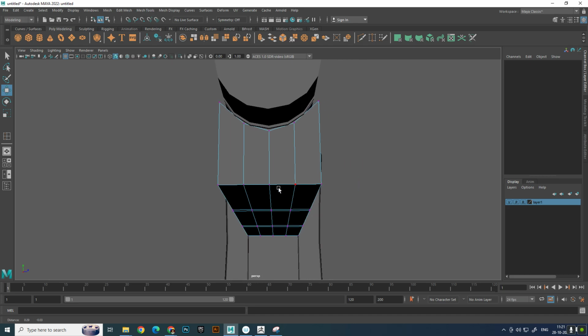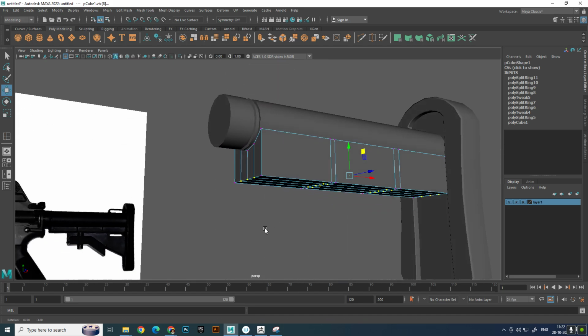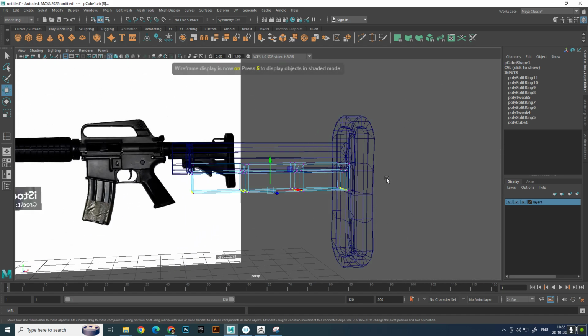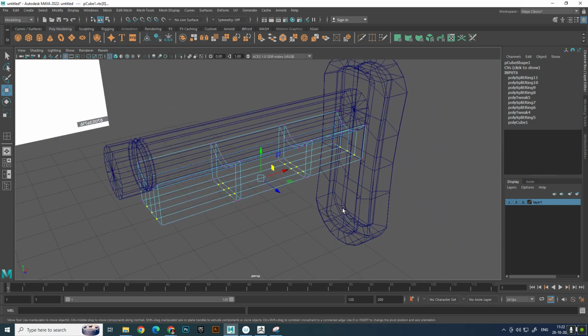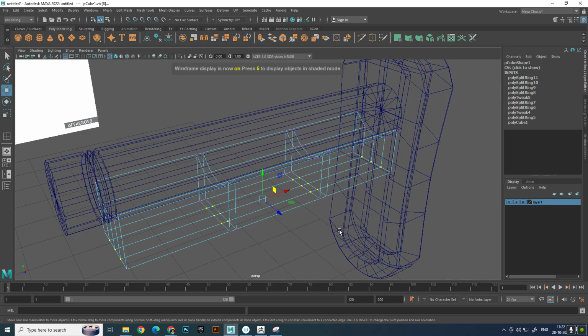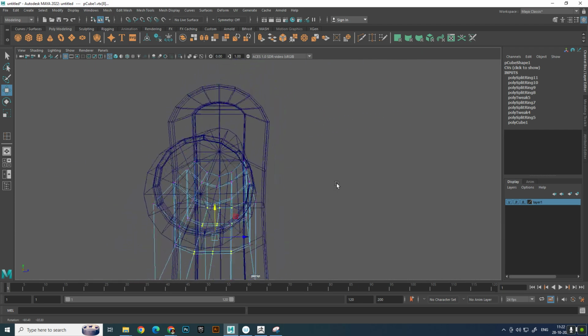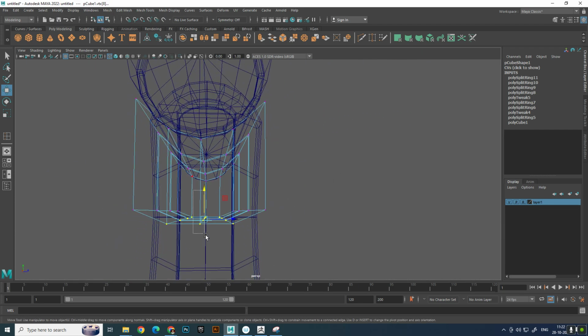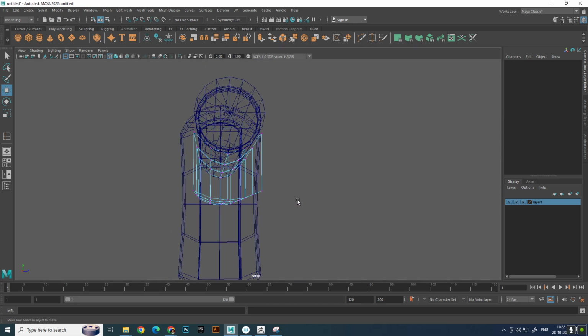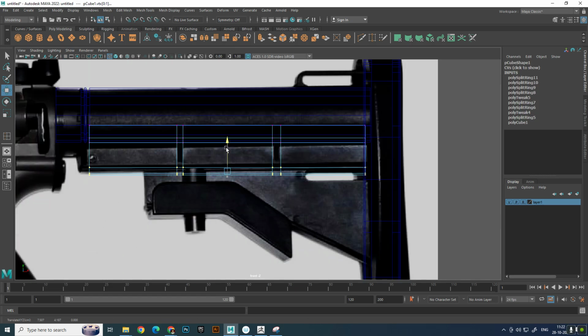Press W, bring this area a little bit down, deselect the unwanted connection, press 4 and check if anything unwanted has got selected. Pull down, press 4 for wireframe and 6 for color mode, so you can check for unwanted connections. Can you see the depth, round shape? So try to pull down, keep it here exactly, this is a face, and come down and bring it as well.